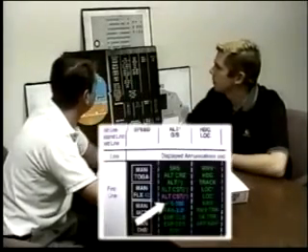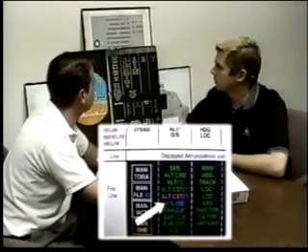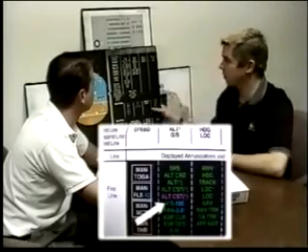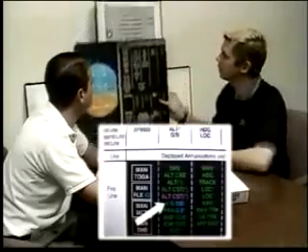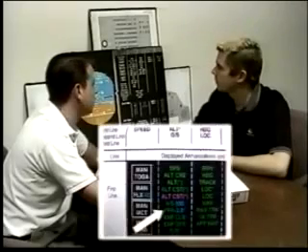How would you get a selected vertical speed? Selected vertical speed is done by pulling the vertical speed knob here. And what that gives you is a reference to a vertical speed. If I want to constantly descend at 500 feet per minute, as this indicates, then I'll pull and ask for that. I could ask for a climb as well, but it's just giving me a speed, or a vertical rate of climb. What about FPA then?